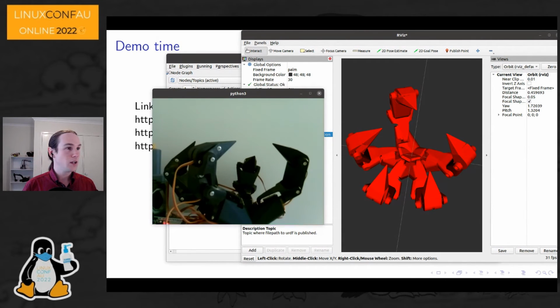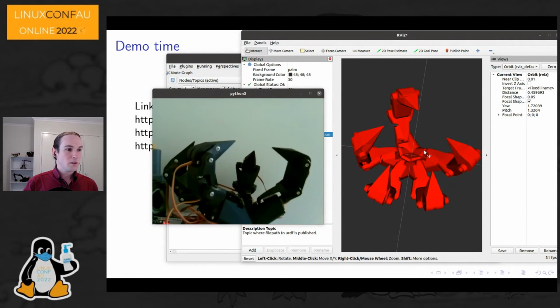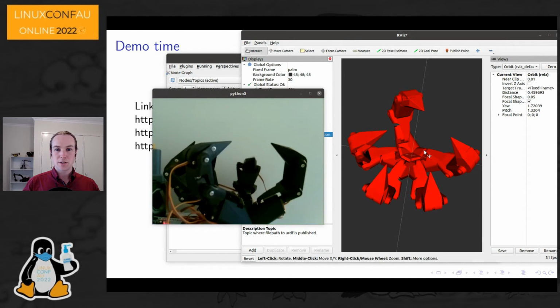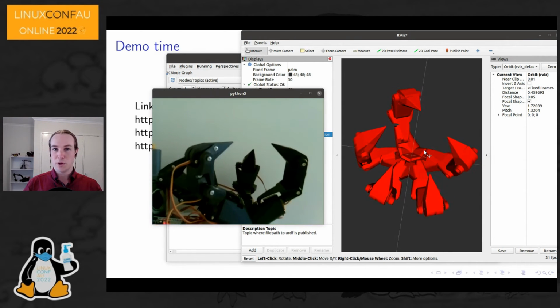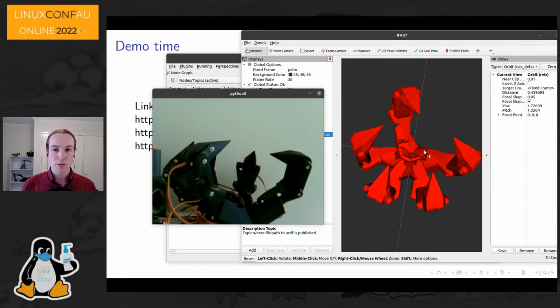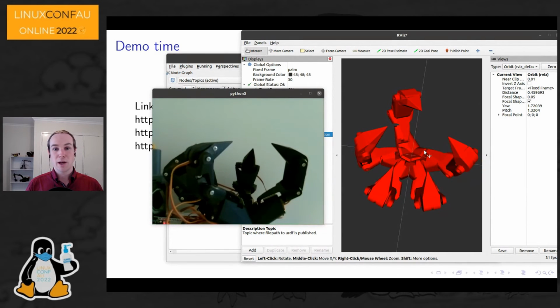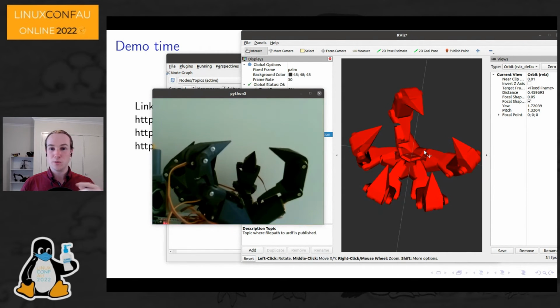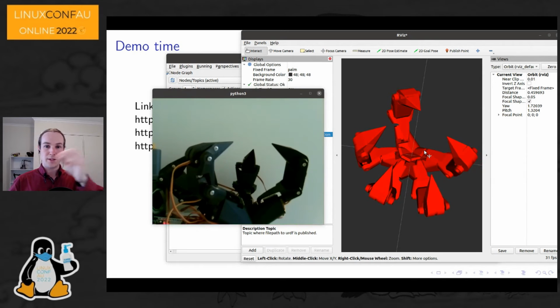In the case of this claw, I've got the contact points where the claw should be moving around a circle. Kinematics is essentially where that contact point ends up for a given motor motion. Inverse kinematics is figuring out how the motors should move to achieve that desired motion.